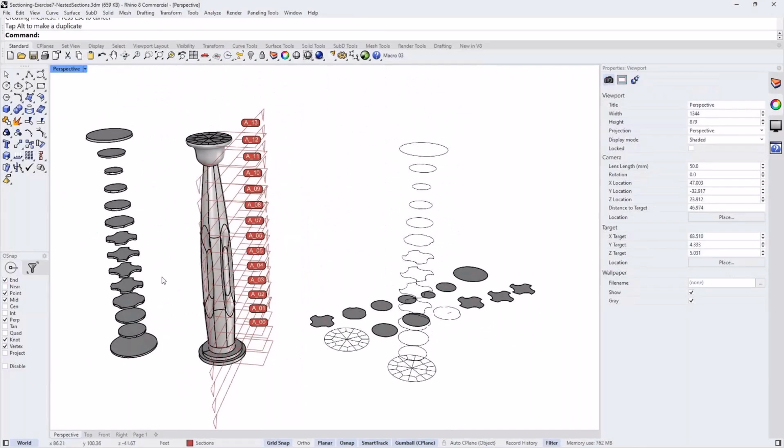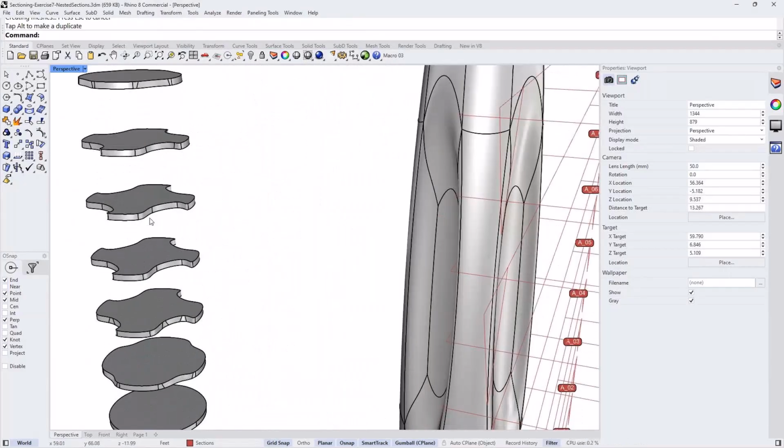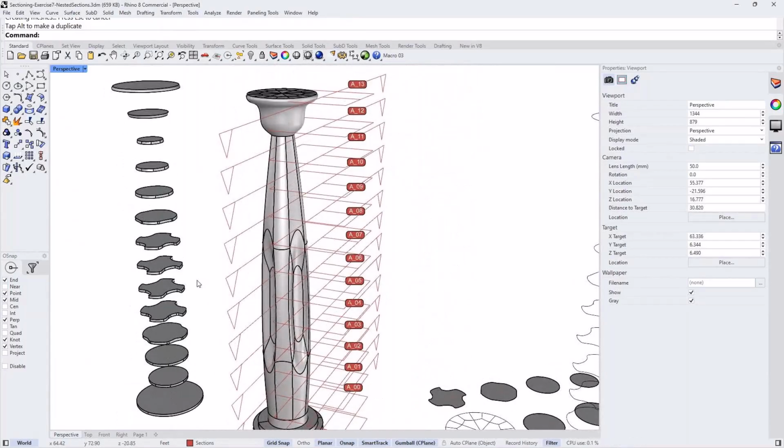And if you're doing routing or what have you, then you can project them on the XY plane, nest them, and then you can just create a routing through. You can cut a sheet of wood and then stack it or something. But yeah, so these are actual slices. They are not extrusions, if you will. So if the slice is thick enough, you'll see the bending that's happening on the sides of it. Great, thank you. And they both are history enabled. So if you want them to follow the model, they can follow the model as well.